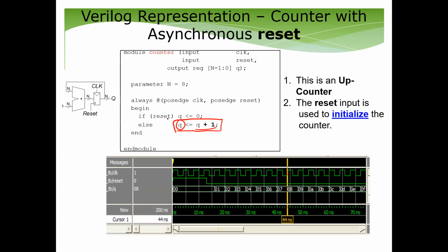One very important thing to note is the reset signal. When we check on it, if it's a normal counter, we'll just reset it to 0. A reset signal depends on whether it's an asynchronous or a synchronous signal. In this code, this is an asynchronous reset with an active high reset. To differentiate, if the question did not specify by writing active high or active low, we should know that from the name of the signal.